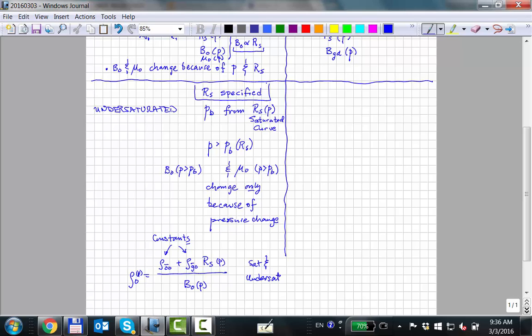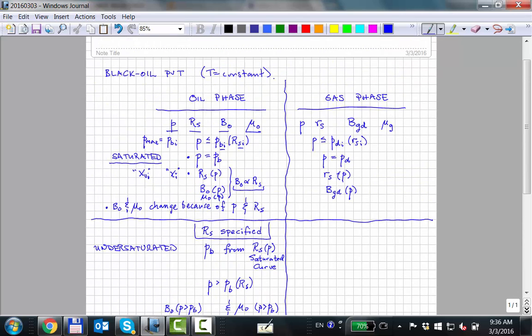But in finding whether you have undersaturated oil, you have to first know the GOR. You have to see that that GOR is within the range of RS values in the saturated table, 1,000 cubic feet per barrel. Because you remember our original example yesterday was 200 cubic meters per cubic meter. Times 5, that's 1,200 or whatever. I know it's 1,000, but it's a little bit more. So that GOR that we have has to be within the range of the RS values. If it's within that range, it means that it's going to be an oil.